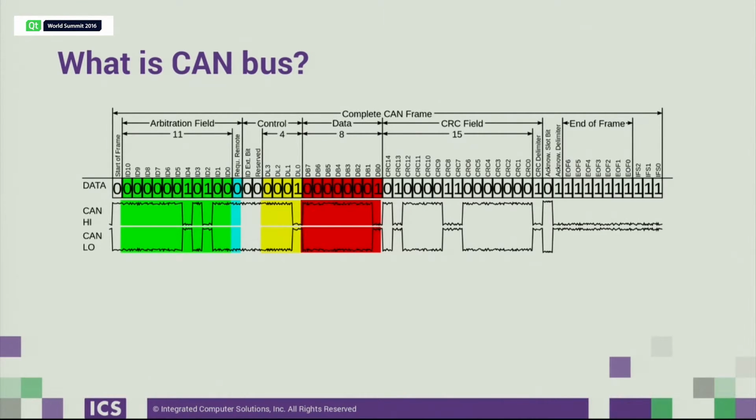So typically everything on the same bus is connected through a 2-wire bus over a twisted pair. It's designed for vehicle type environments, and the bit rates are up to about a megabit per second within a 40-meter size limit, which is fully acceptable within something like a vehicle.